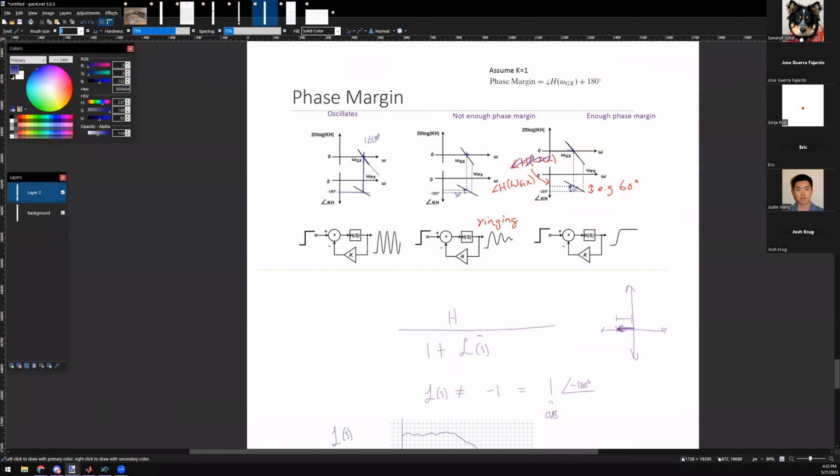It all comes from the fact of this guy right here. Does that make sense? But we generally have a phase margin of 60 degrees to have a clean response. You will find that standard in industry, especially automotive. Automotive will require any negative control feedback system to be able to measure its feedback to be 60 degrees phase margin. That's very common in automotive platforms.